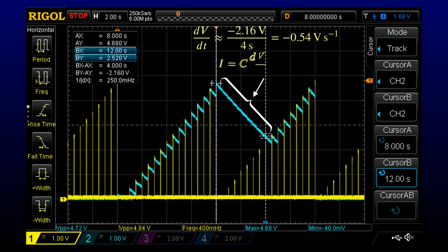That rate of droop corresponds to a current of 5.4 nanoamperes. That's a tiny current, but obviously it's enough to mess up this sensitive circuit. But it's so very small that we're going to have to start looking at non-ideal components.